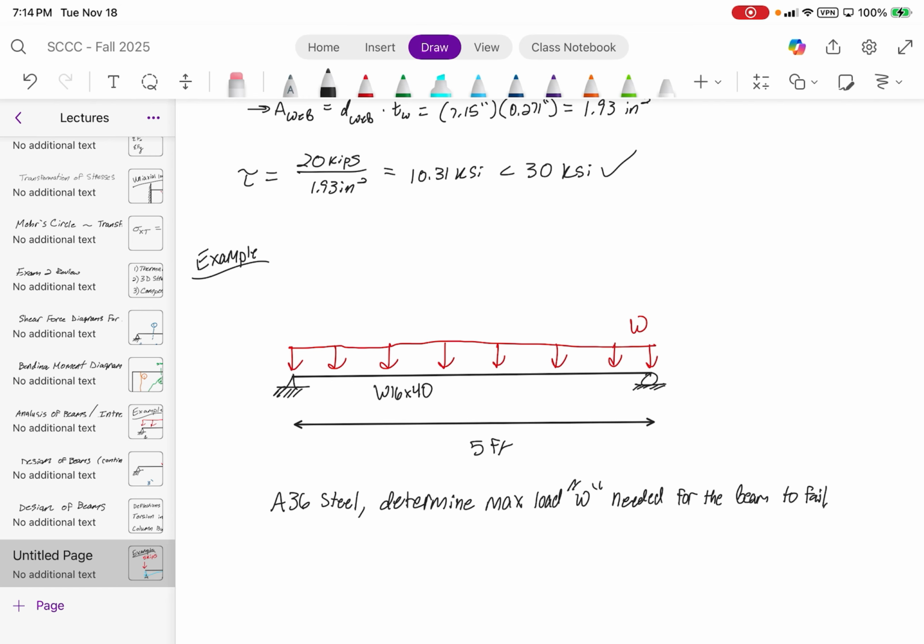Yeah. We can divide them or? Multiply them because stress is equal to M over S, which then you rewrite as M is equal to sigma times S. Oh, I divide. Yeah. With that problem, you don't know what the bending moment is, so it's kind of like going backwards on our problems. You multiply with Sx by what? Rx? The stress. No, Rx is the radius of gyration, which only comes into play for buckling. So don't even look at Rx. The only two things that you should be worried about are Sx and Ix, because they're related.